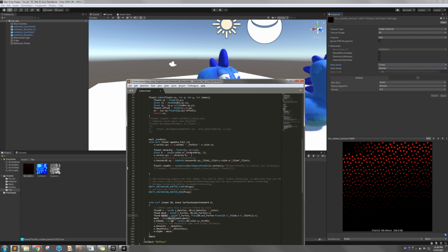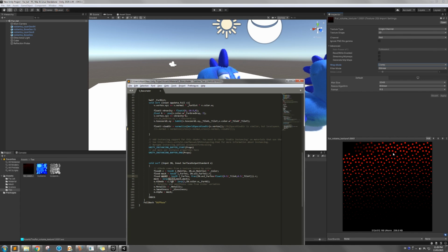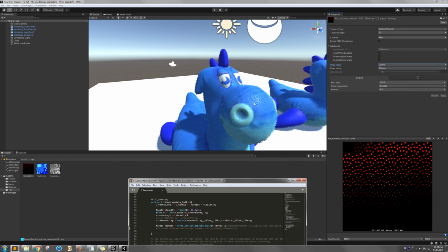This UV is modified inside the sub UV function. So to make the tiling, I use a fraction. When adding the half size of this section goes over 1, it wraps back: for example, 0.3 plus the offset gives 1.3, and it goes back to 0.3. So I really need a fraction here. Then you have two masks. The second one is offset, so I use lerp to mix them together, and also add the fur AO here.